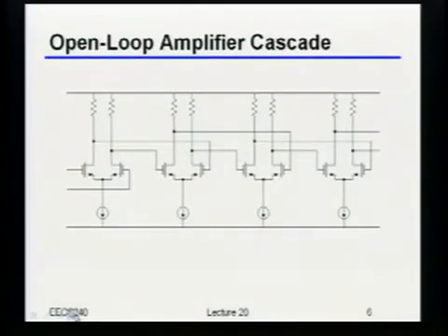But if you take a bunch of single-stage amplifiers and put them into a cascade, you can very grossly break the gain bandwidth limit. This gets into lots of interesting discussions. For single-stage systems, what was always trading off was gain and bandwidth. But with multi-stage systems, you actually have another degree of freedom. That extra degree of freedom is the delay.